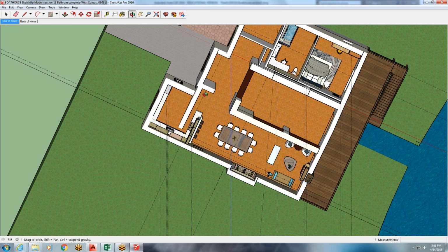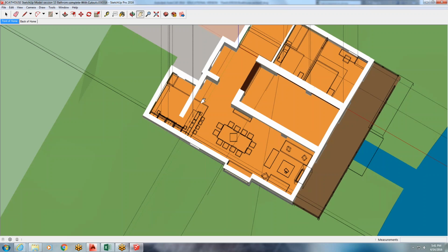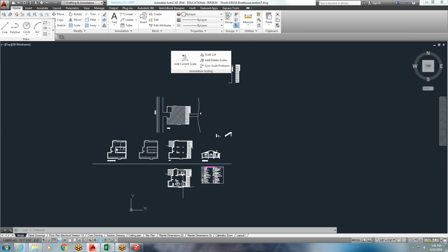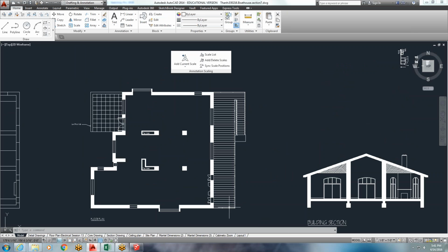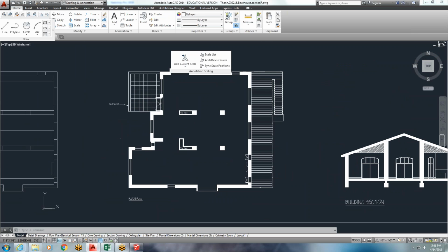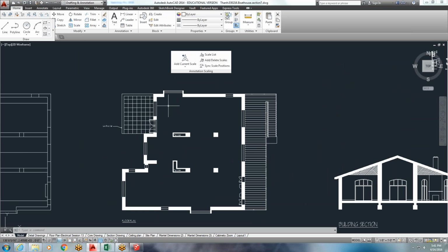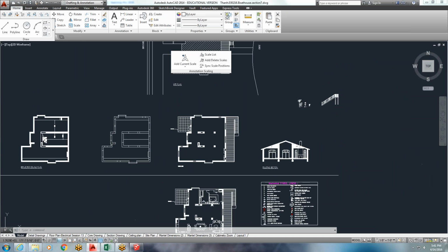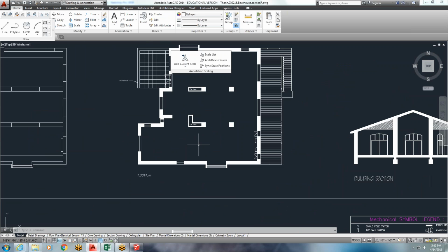So I, at this point, know that I want to go back into my AutoCAD where I did have this big empty space of a floor plan, and I want to fill in my furniture and also add the walls that were missing. So for the furniture, I'm suggesting you try to see what happens when you export it from SketchUp. So you're left drawing as little of that as possible, but it gives you more detailed blocks than you might be able to download from an AutoCAD resource online.